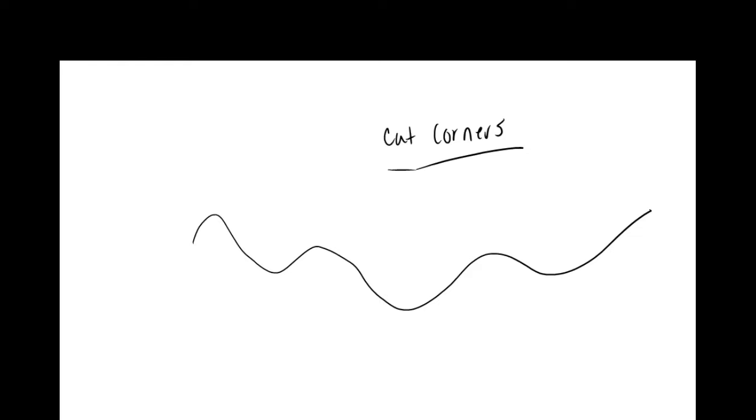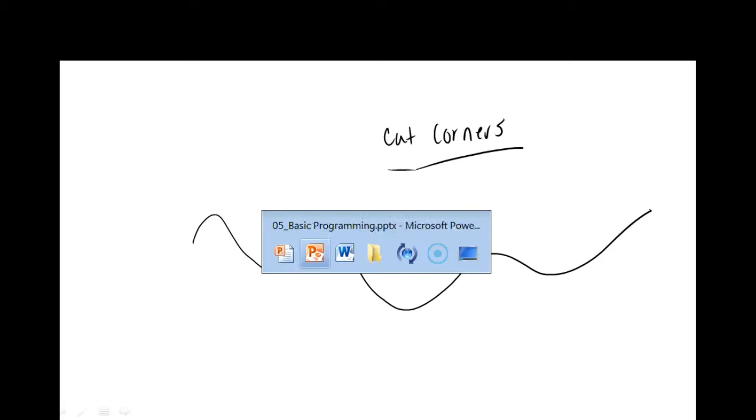You understand that? So I can follow a cut. Instead of me following a curvy line using linear moves and circular moves, we cut corners while we're driving all the time. That makes sense. What we do in robotics, that corner cutting, we refer to that as round off.